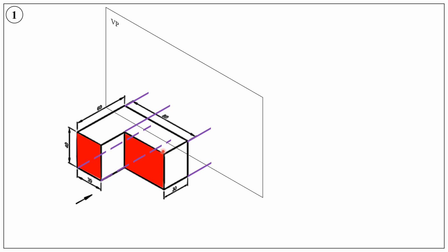The points of intersection obtained on the vertical plane of projection are joined in a proper sequence. The front view will look like this. So it becomes a rectangle. You can notice there is a vertical line inside this rectangle. So what is this vertical line? This vertical line corresponds to this edge.